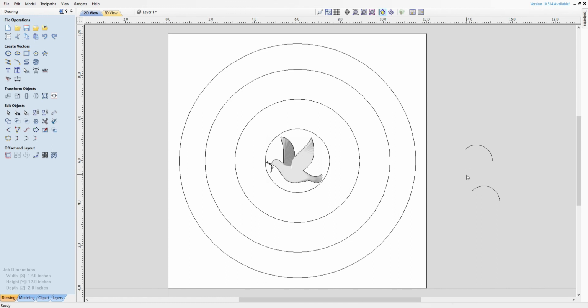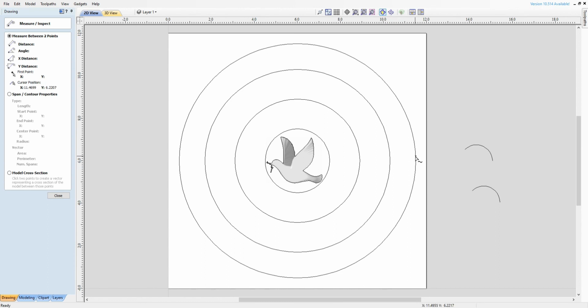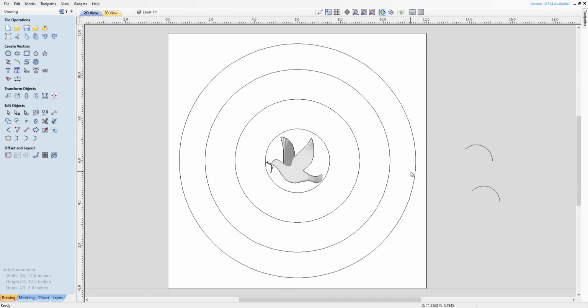And how I arrived at the dimensions, I took my measuring tool, came over here, and I measured the distance from there to there. It's 1.2 inches. And that was the size of my circle, 1.2 inches. And so that I didn't drive all the way down deeper than needed to be, that's why I cut that where I did. It was just an experiment. So you can do what you want. You can try doing the whole 180 degrees, or you can chop it somewhere else. Whatever you think.